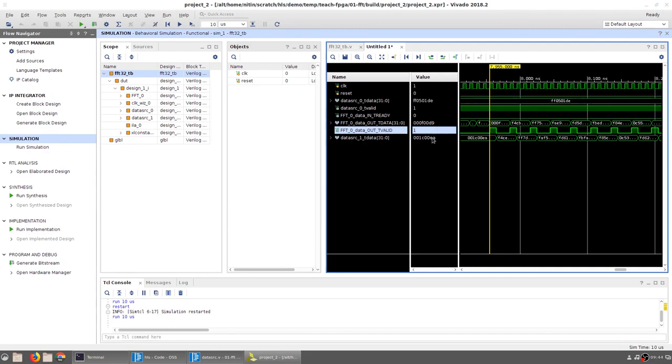Remember that the D9 and the EA are both referring to the portion that is in the fractional part, because this is 16-bit data with an 8-bit fractional part. What about the next output, F4CB? Well, the expected output was F4CE.